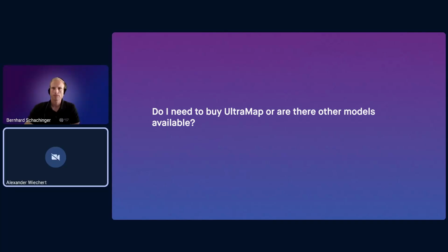Then you have the choice either to continue in the UltraMap workflow, which is a highly integrated workflow, and all the modules are integrated into one user interface, working on one database, and so on. So you have a lot of benefits if you continue your processing in the UltraMap workflow: run your AT in the AT module, run your dense matching, generate your DSM, DTM models in the dense matching module, use the UltraMap ortho pipeline for your ortho projection for DSM and DTM orthos, and then jump into the 3D module for your 3D TIN generation.